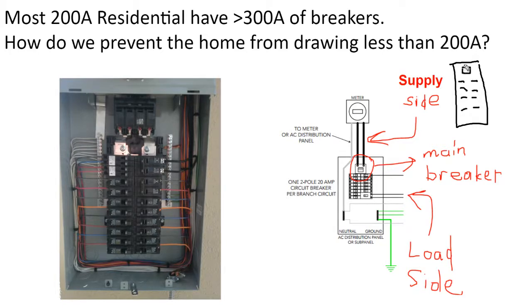But if simply offsetting the electric bill is the goal, easier project logistics can result from simply landing the solar array or the battery inverter or both at the bottom of the bus bar. A supply-side connection requires a power shutdown from the utility. A load-side connection does not.